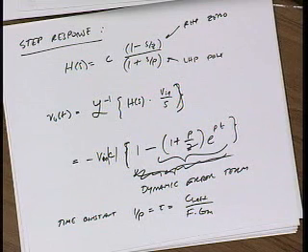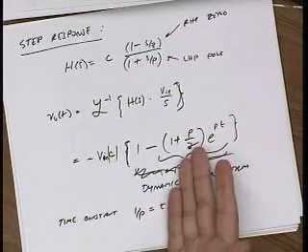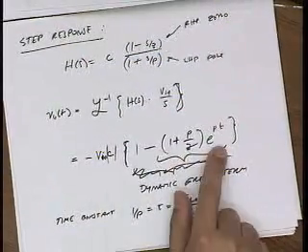What would be the bandwidth if I made the pole and the zero the same? Yeah, I would have infinite bandwidth, right? What's wrong with having infinite bandwidth? I'll buy that, right? Is it physical? Can you get infinite bandwidth out of this system? Why not? We just did the math, right? The math says that if I make P equal to 0, this term goes to 0. It settles infinitely fast. There is no settling time.